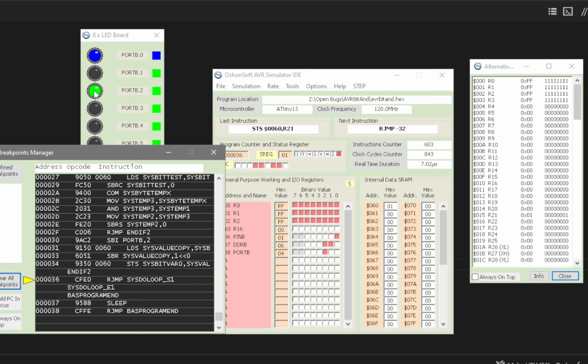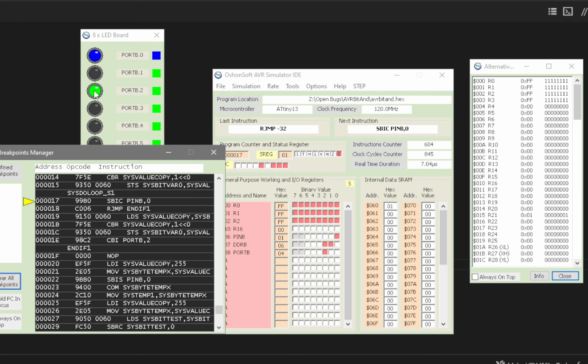Cycle through. It then goes back to the do loop and comes back round again. There's the no op. The next test, again, sets these temporary variables to 255. Test bit 0. Now this time, it is still set, but we've unset the latch. The latch has now been set to 1. And remember, it has to be 0 to turn the LED on, but the LED is already on. So how does it do that?